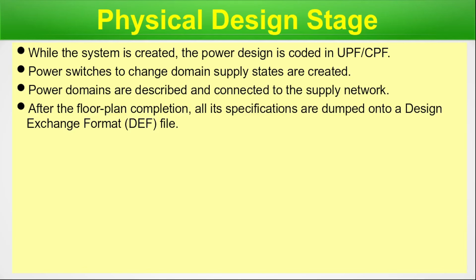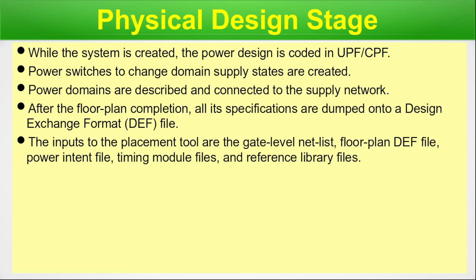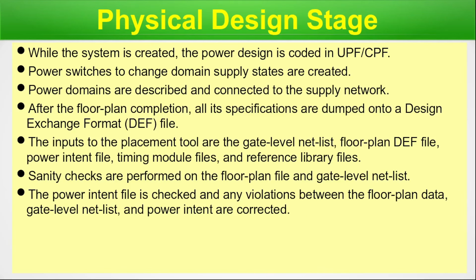After the floor plan completion, all its specifications are dumped onto a design exchange format, that is the DEF file. The inputs to the placement tool are the gate level netlist, floor plan DEF file, power intent file, timing model files and reference library files. Sanity checks are performed on the floor plan file and gate level netlist. The power intent file is checked and any violation between the floor plan data, gate level netlist and power intent are corrected at this stage.